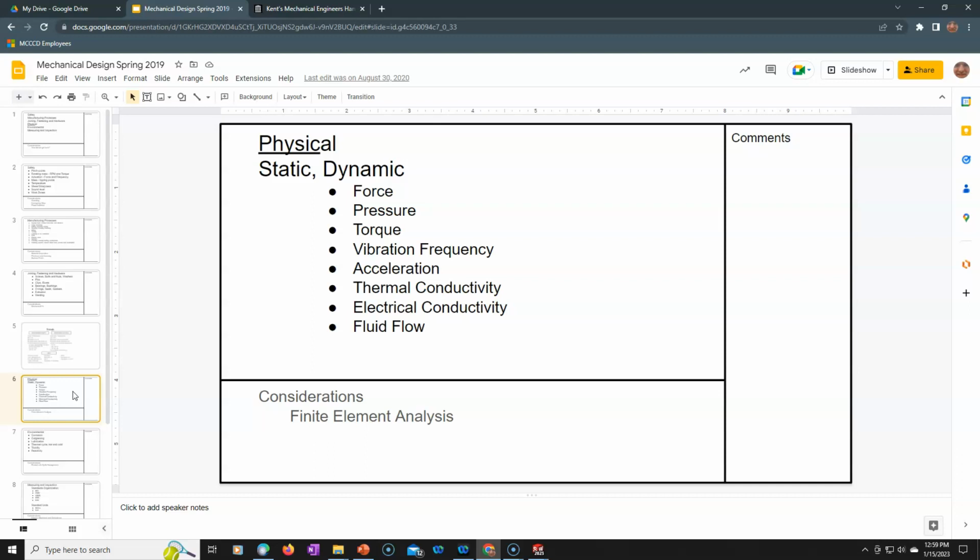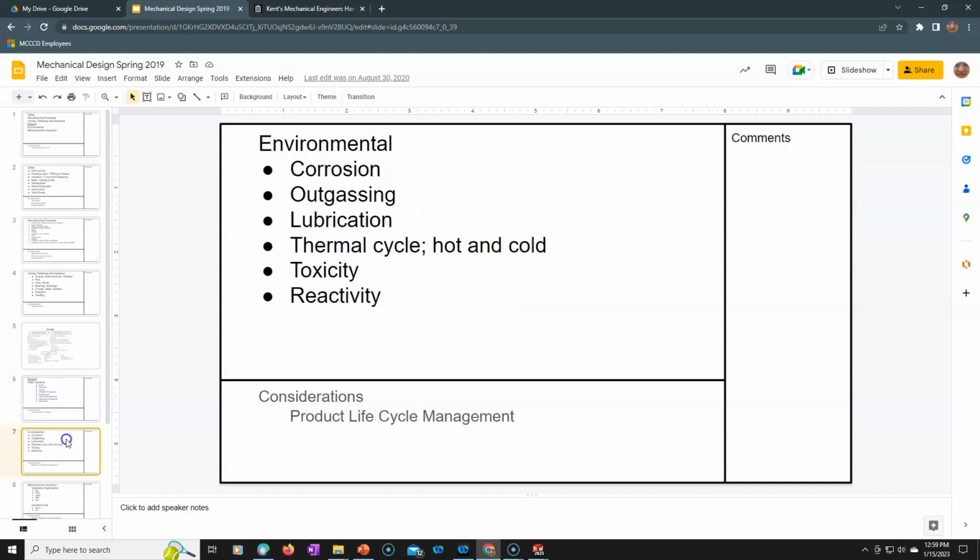So these are where we get into the finite element analysis or simulations, where we're looking for the gross errors. I don't expect my simulations to tell me everything. I cannot account for every last detail in the process of using the software, but I can get enough of a sense of whether the direction I'm taking is over-designed, overcompensated for materials, or undercompensated, and I need to beef it up a little bit or can reduce it down.